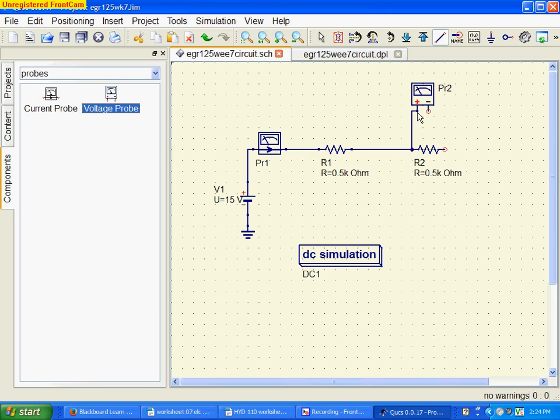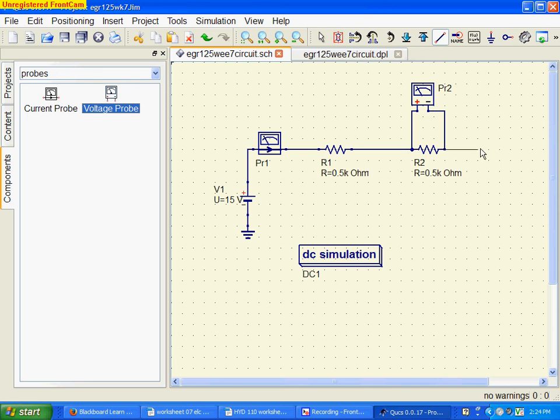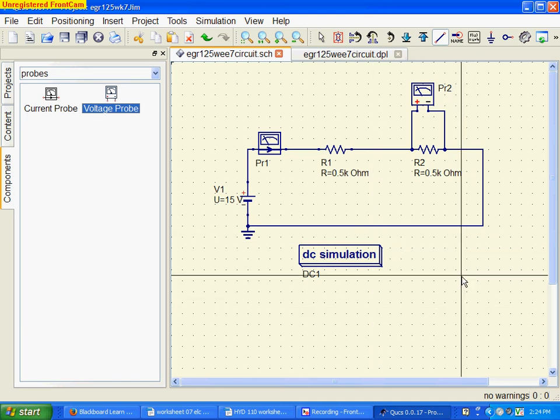Save and simulate. So I'm going to go over here and hit save. Got my project saved. Hit simulate. The longer it takes to simulate, the longer that window will be up that you briefly saw. Where's my voltage probe? Well, I've got to click in the box and tell it to add it. Probe 2 is voltage. Click OK. Showing me 0.75.